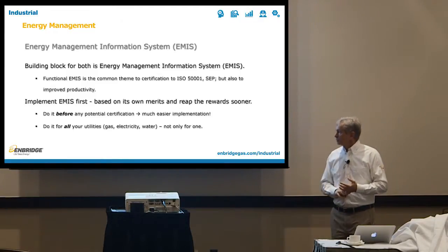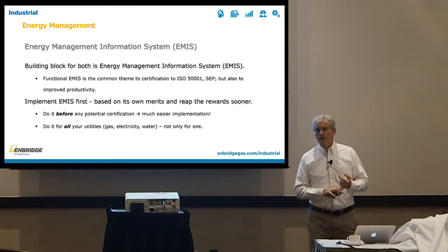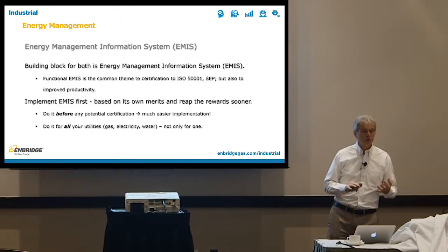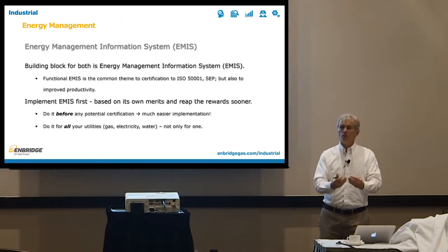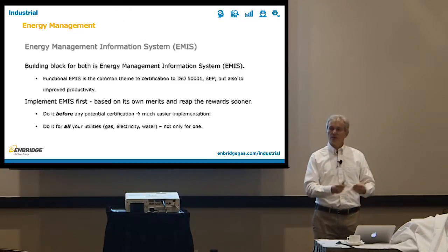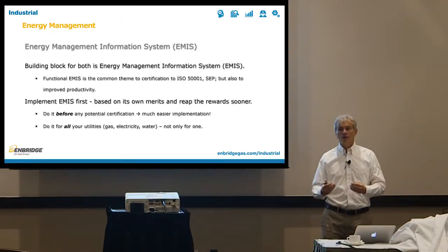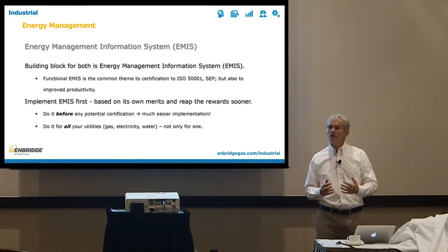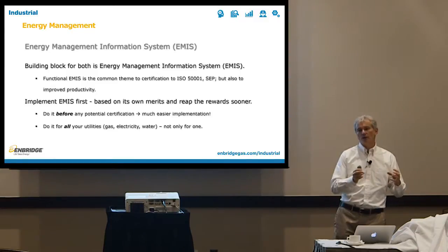One thing that I would also like to stress is that if you're going to do energy management, do it for all the utilities. Don't do it just for electricity, don't do it just for natural gas. Do it for all the utilities at once. Because the message to your people who will ultimately be responsible for delivering on this energy management will be much easier if you say it's important to save electricity, but it's also important to save gas and water. It's going to be a lot harder to say, well, as long as you save natural gas, I don't really care how much electricity you use. That's not the same message. Psychologically, that's not how people will react best.